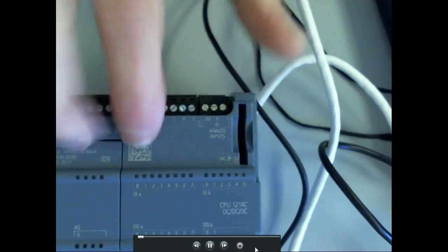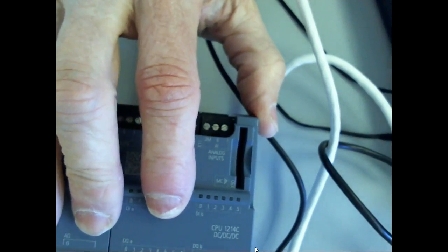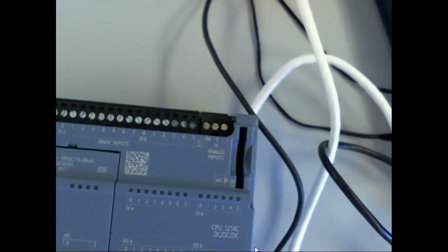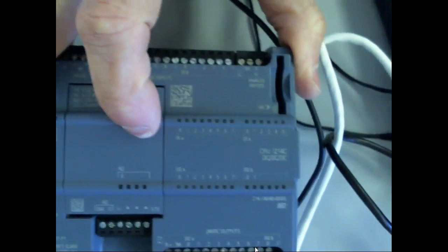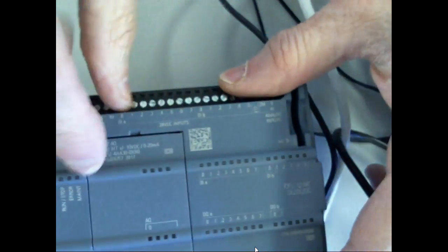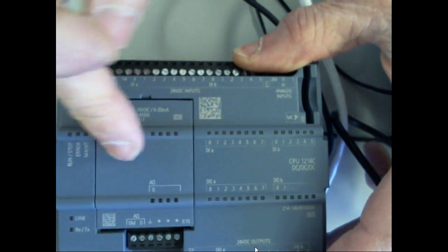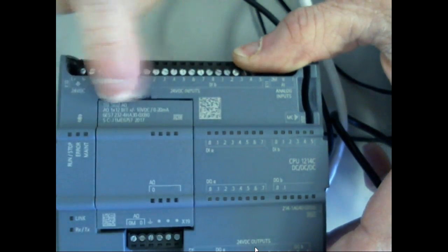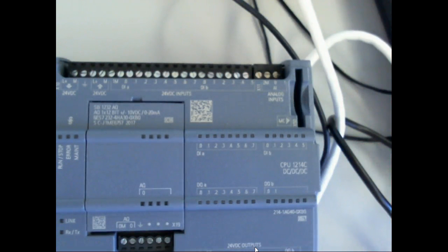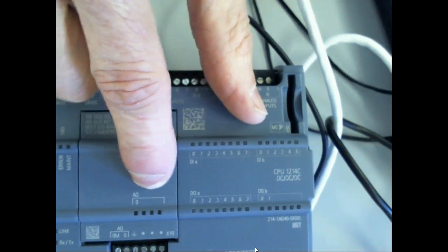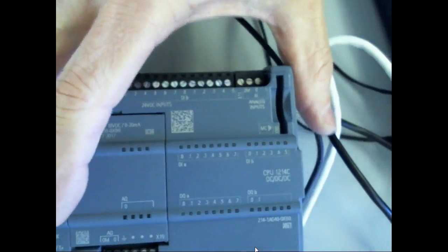So fixed and modular both have advantages over the other. But most of your small PLCs like this are actually hybrid units. You can use them as fixed, or you can upgrade them by adding different modules for what you want. In fact, they've got a little slot right here, and this pops out. This is another module that we can add. What we did here is add more analog. The PLC comes with two analog input ports, but what we've added here is analog output, which is pretty neat. This is unique on this Siemens PLC.